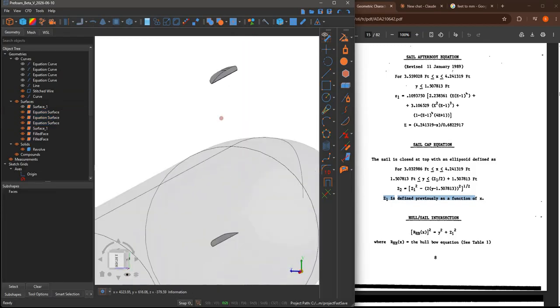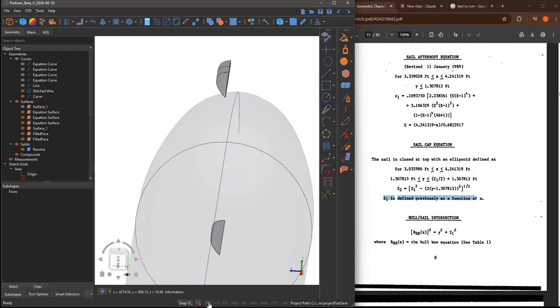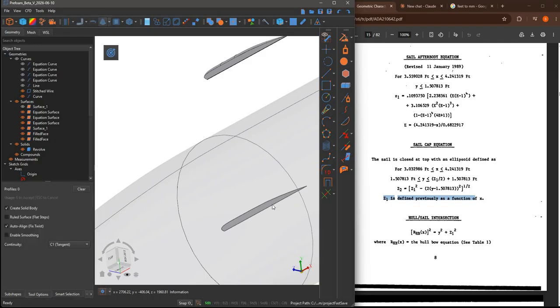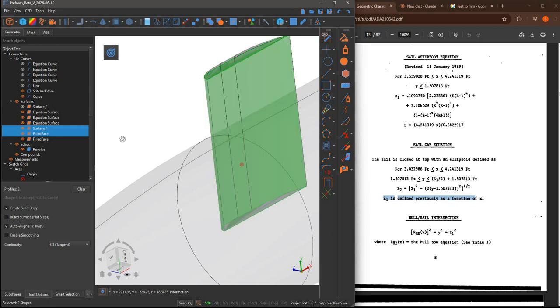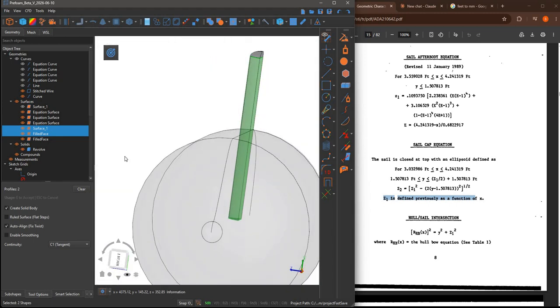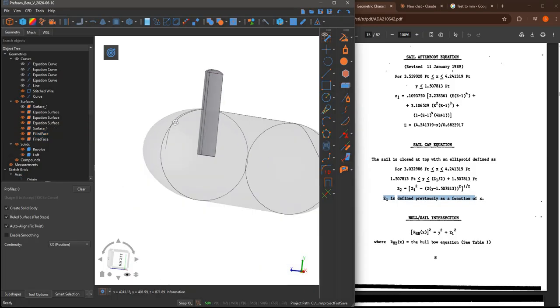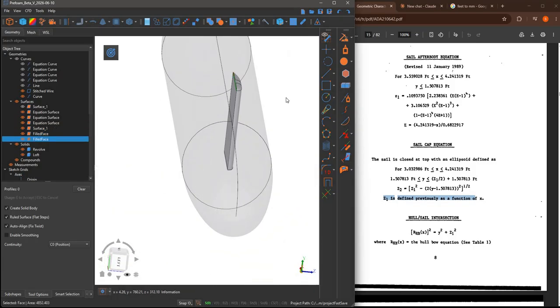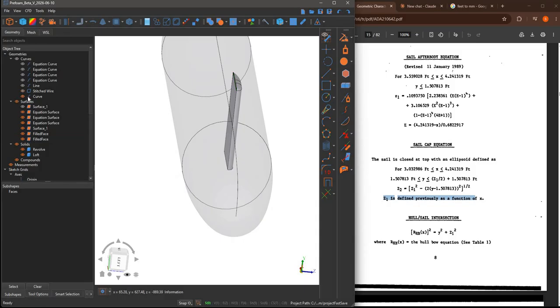So what is now missing is the connection. So I will call the loft tool, and then I will hit this face, and then this face, and if I hit OK, you will see that the geometry looks okay now.